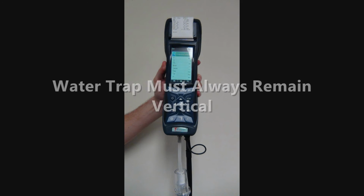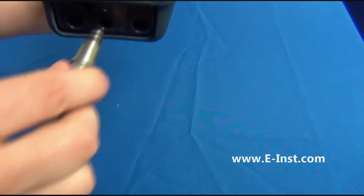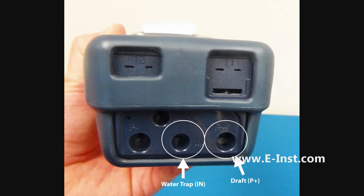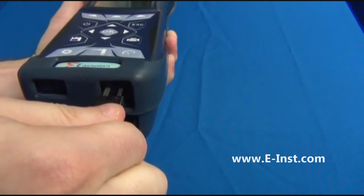The water trap must always be in the vertical position during all operations of the analyzer. Now let's connect the probe. All the connections on the units are form-fitted to prevent you from plugging in the probe hoses incorrectly. The water trap plugs into the middle port at the bottom of the analyzer labeled IN. The other connection is for your draft and pressure measurement, and that connects to the P-positive connection on the bottom right of the analyzer. Plug in the thermocouple connector at the bottom of the instrument for your stack temperature measurement.